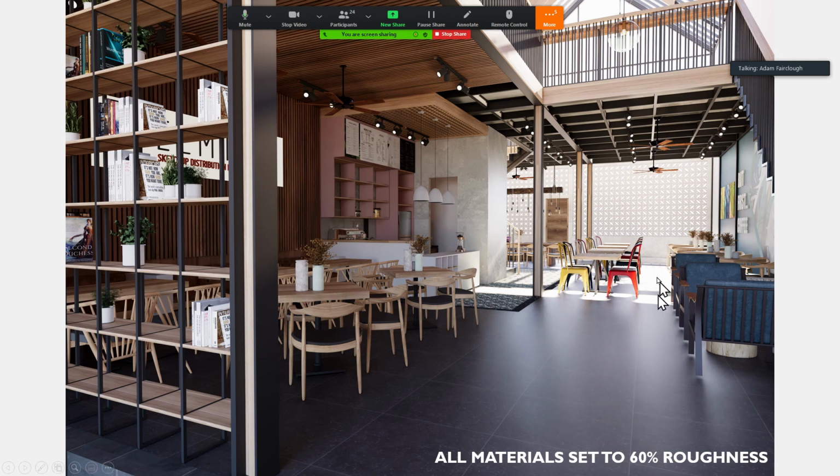We will often see reflections even on things that we might consider to be quite rough. We know that if you're outside on a road on a hot day, we can see reflections even on quite a coarse concrete. We can see it on painted walls. This is a mistake a lot of people working on interiors make, where they think, I'm using a Farrow and Ball paint, which is very matte in the scheme of paint, but actually it reflects back quite a lot of the environment, and you'll see this all the time. So we can make some quite big broad stroke changes to the way our images look simply by bringing back some of the reflections that Enscape by default has chosen not to show. I'd like them to change that value as a default, but never mind.